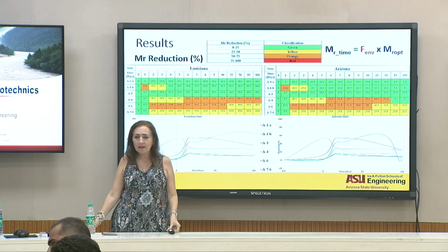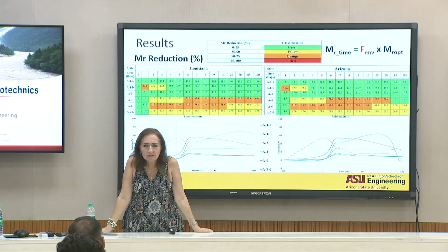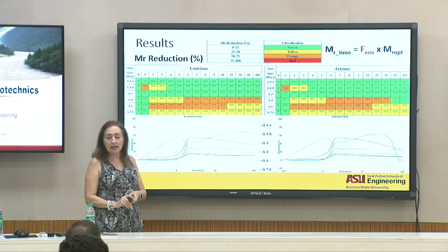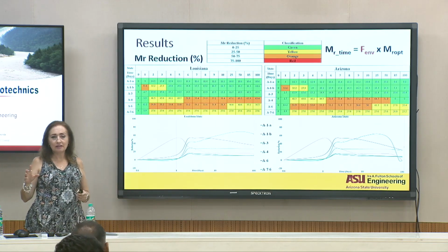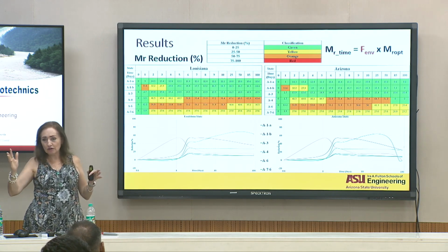Basically, do you assume it to be elastic in nature? Whenever there is a loss, sorry, that modulus behavior, do you take it as an elastic response? Yes, this is elastic. This is a resilient modulus. When we talk about a loss of 50%, 60%, in that case it recovers exactly. You will recover exactly. So, as a matter of fact, the equation is an elastic model equation.